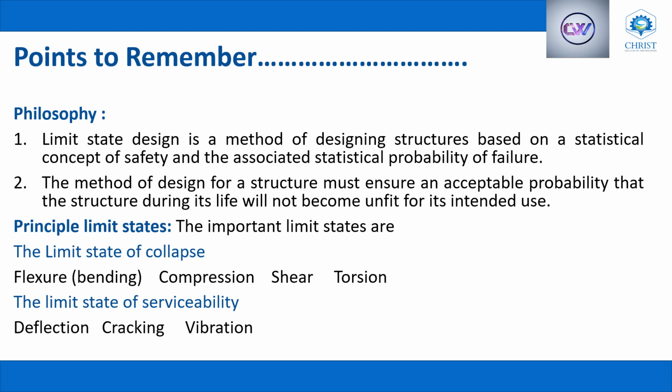Before moving to the questions, we have to remember some important points about the philosophy and the principal limit states. So let's move on to different points. First one, philosophy. Limit state design is a method of designing structures based on a statistical concept of safety and the associated statistical probability of failure. So in the limit state method, we are designing structures based on probability.